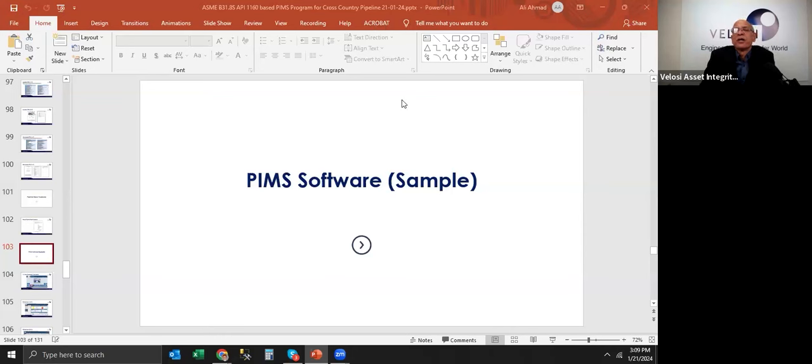His question is, can API 1160 be applicable for natural gas as well or for gas only? In general, the answer is that API 1160 is for oil pipelines, and ASME B31.8S is for gas pipelines. But what I said earlier, if we develop one system for gas, a similar system is applicable to oil as well. So as such, we don't need to produce two systems. Both systems are basically interconvertible and can work jointly, right?